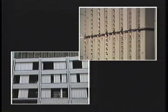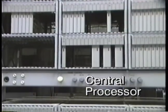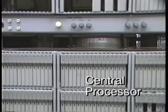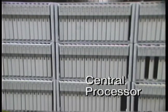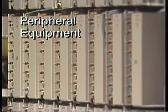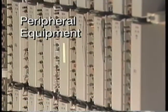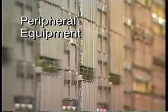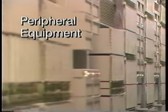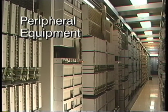To provide switched service, the analog electronic switching system is comprised of two basic parts, the peripheral equipment and the central processor. The central processor is a computer that provides the intelligence to control the switching operations. The peripheral equipment consists of all switching circuits and devices that establish the physical paths between lines or between lines and trunks. Many components are included in the peripheral equipment of the analog switch. In this segment, we will examine some of the key peripheral components.